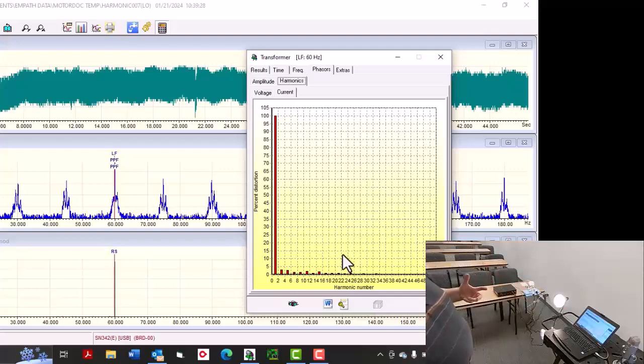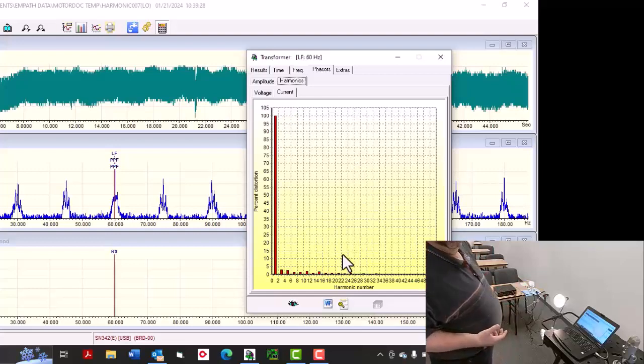the whole system. So if I added in my fluorescent lighting system here, I have not gone over to LED at this point, but I'm running T5s. So if I take my T5s and I go back and I take my measurements, I'll have distortion from that, and then I add in LEDs, and in my whole system, that's going to create an even higher thing, but back at the panel, not right at the system.